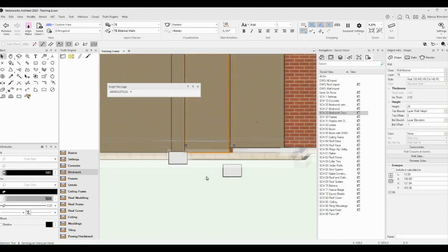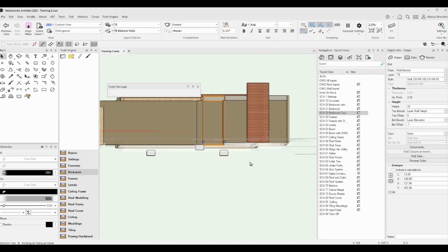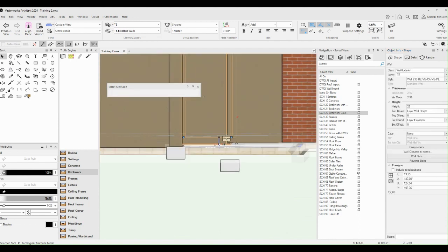Now technically that's not correct for that cavity wall, because internally still needs to go back to 0. So what I'm going to do, I'll put that back at 0. You see that go back up to 0, and that's now -2. So I'm going to change that external leaf and the render to go down one more course, and we do that in the component screen.